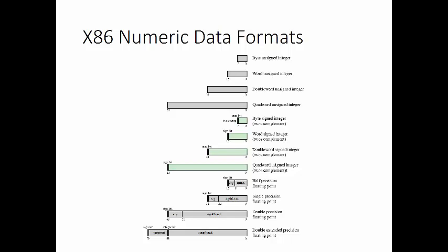And like I talked about in the last slide, there are also the single instruction multiple data types. These were introduced in the x86 architecture as part of extensions to the instruction set to optimize performance on multimedia applications. There's an example with fade in and fade out. In terms of ARM, processors support data types of 8, 16, and 32-bit word length, 32 being the word, 16 being the half word, and 8 being the byte.